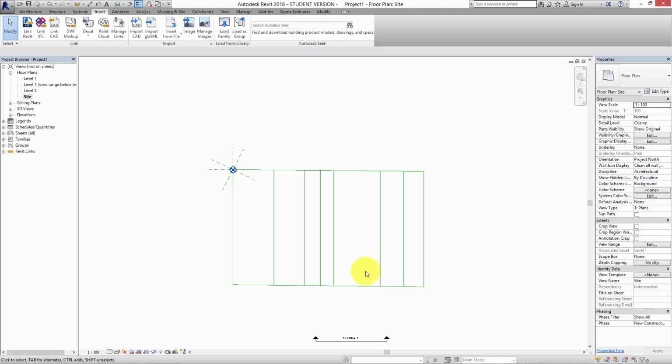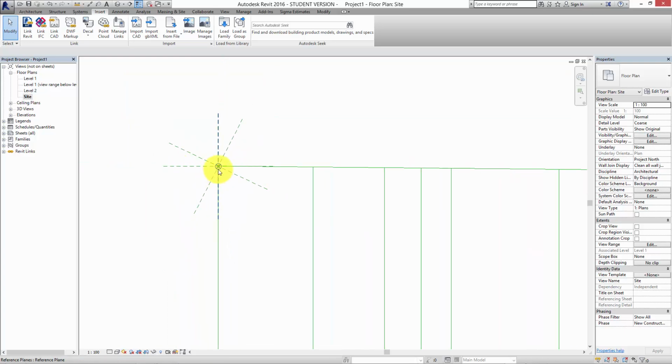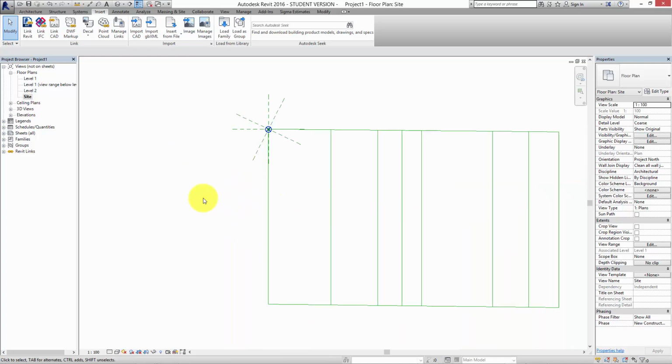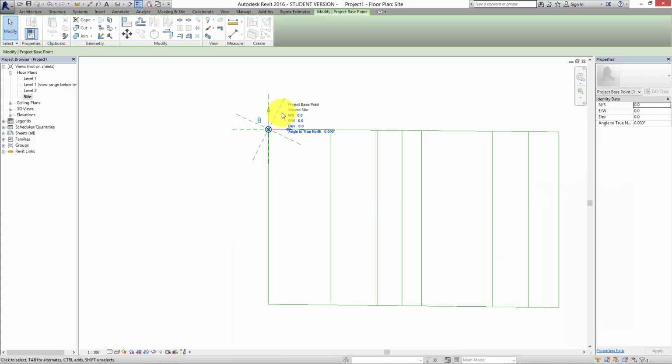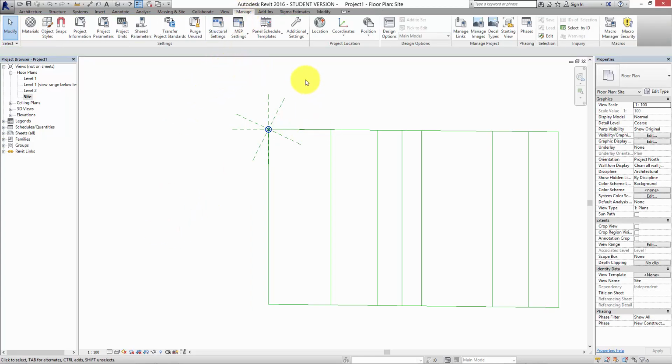So open. It comes in, and you can see that the two blue symbols here are on top of each other. So it's come in at origin to origin. That's the origin right now. If I go and try and select the blue element again, you can see that it's still set to 0. But if I go into Manage and Coordinates and press Acquire Coordinates,